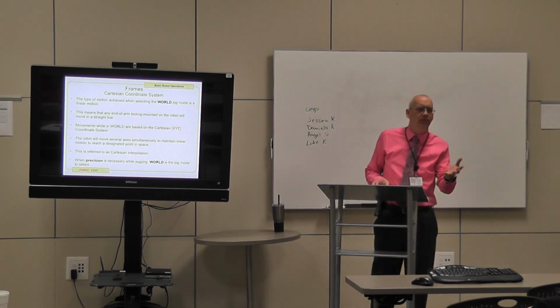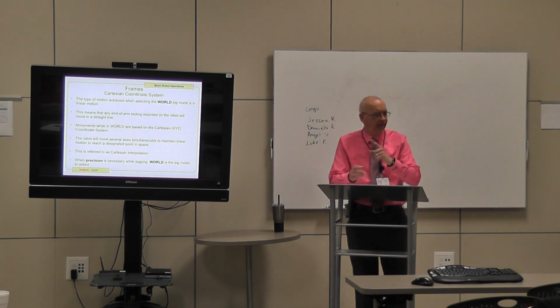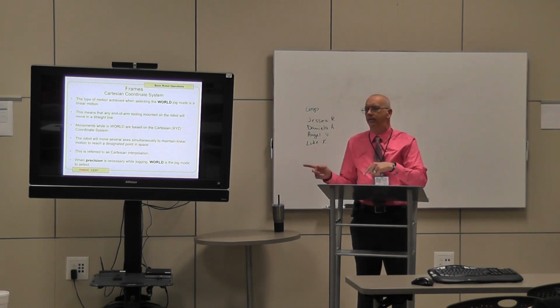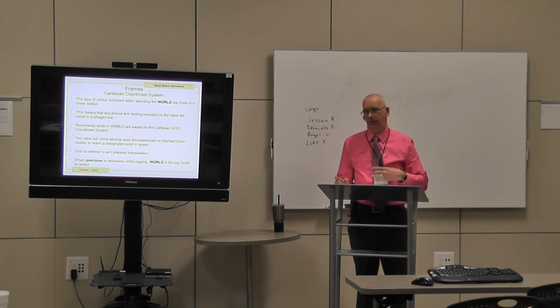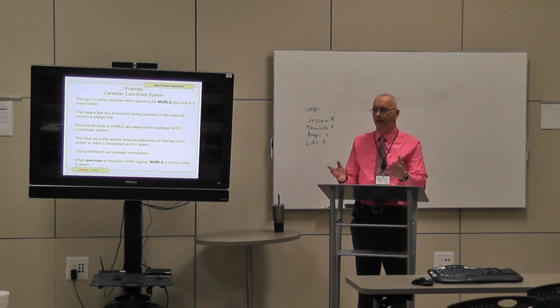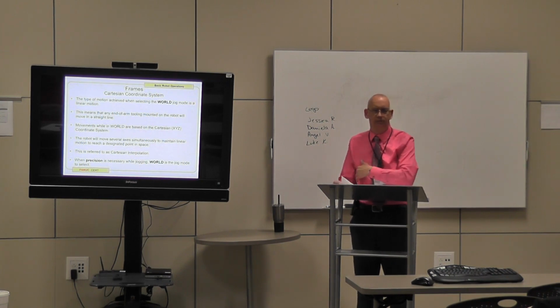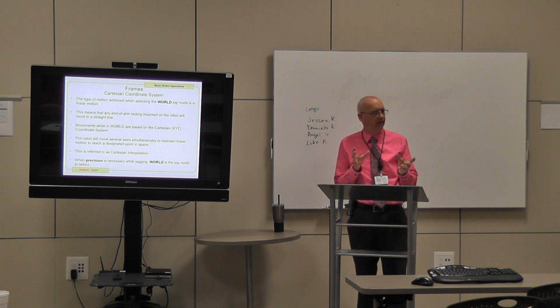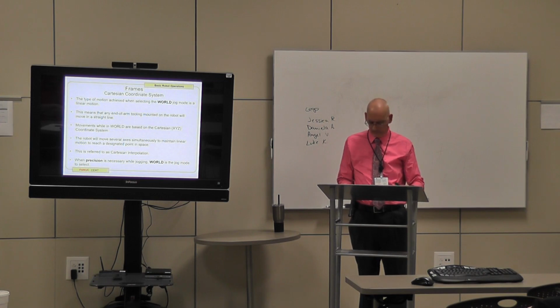So when we were in joint mode, we were moving each joint individually to get to where we want to go. Once we learned about how the world frame works, and knowing that it works in a linear motion instead of an arc motion, because our joints run on degrees, whereas our world Cartesian system runs on linear, and then it turns into millimeters. Okay?